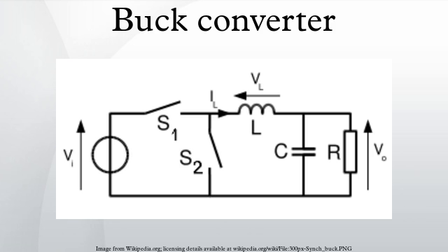From this equation, it can be seen that the output voltage of the converter varies linearly with the duty cycle for a given input voltage. As the duty cycle D is equal to the ratio between the on time and the period T, it cannot be more than 1. Therefore, this is why this converter is referred to as a step-down converter.